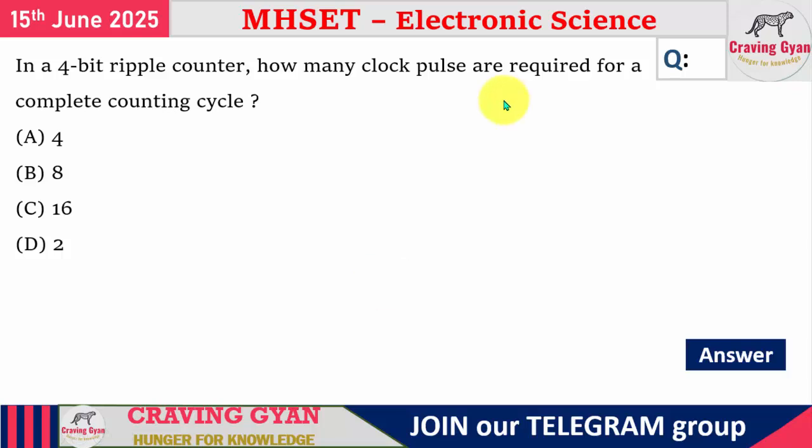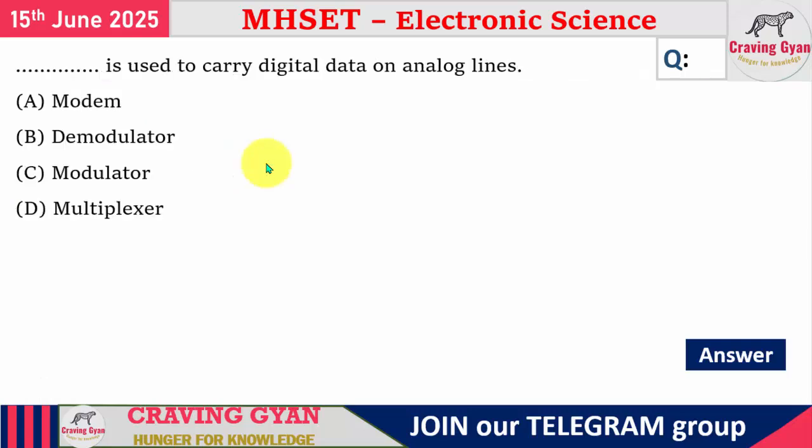In the 7th question, what they have given is a 4-bit ripple counter. How many clock pulses are required for a complete counting cycle? So, in the case of a 4-bit ripple counter, for the complete cycle, you are going to make use of 16 cycles. For this, the corresponding option is option C. Nothing but 2 power 4 will be 16. So maximum cycles will be 16, then the pattern will be repeated.